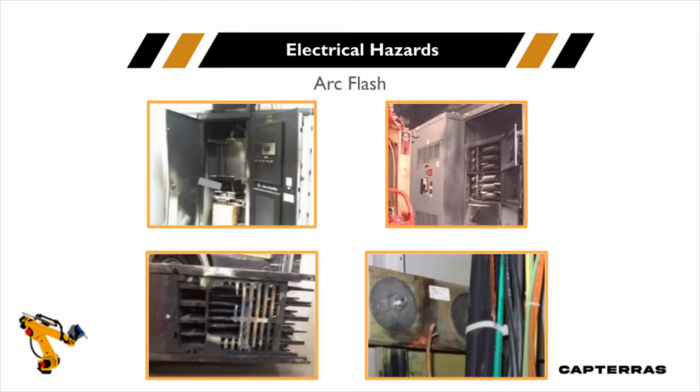It occurred on the line side of the fuses here, and there was an arc flash, and it did blow the door open. So the gentleman here did get exposed to the heat and did get a level of burn, even though the door was closed at the time that he was switching that circuit. On the lower left here, we see a busway, and there was a bus plug in that busway at the time it exploded.